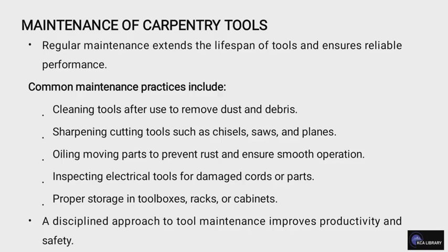Also, you need to oil moving parts to prevent rust and ensure smooth operation. Inspecting electrical tools for damaged cords or parts is important, and proper storage in tool boxes, racks, and also cabinets is also very important. A disciplined approach to tool maintenance improves productivity and also safety.